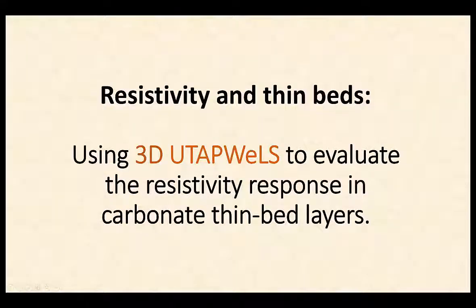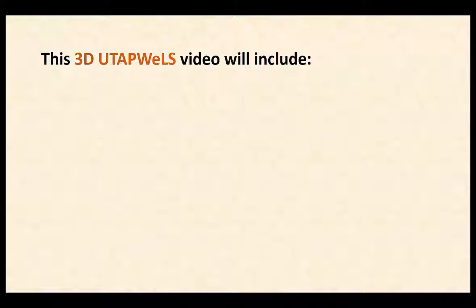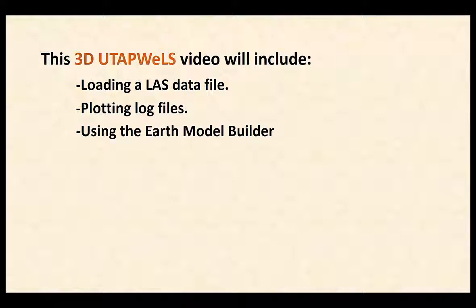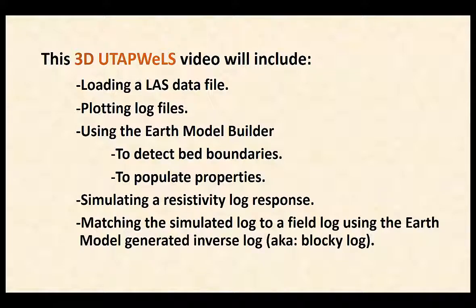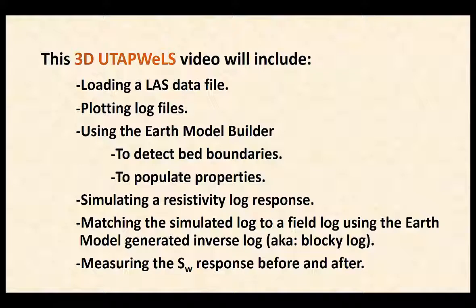This video will demonstrate the use of 3D UTAPWeLS in evaluating the resistivity response in a carbonate thin bed layer example. The following will be demonstrated: loading a LAS data file, plotting log files, using the Earth Model Builder to detect bed boundaries and to populate properties, simulating a resistivity log response, matching a simulated log to a field log using the Earth Model Generated Inverse Log, also known as a blocky log, and measuring the water saturation response before and after.